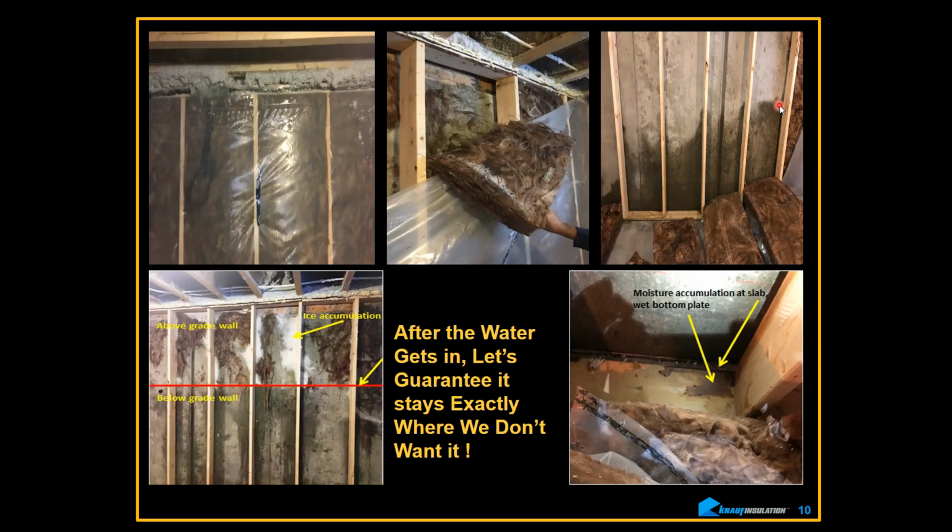So unfortunately, including the inspectors and the building officials, because the rule says that you got to have an air barrier, it doesn't say that it has to be impermeable. So every time I see a basement with a water problem, it's always because, unless it's running in under the foundation, but on a wall system, it's always because it's using an impermeable air barrier. These should only be used in very hot, humid climates or extremely cold climates. The other problem is they get installed incorrectly.